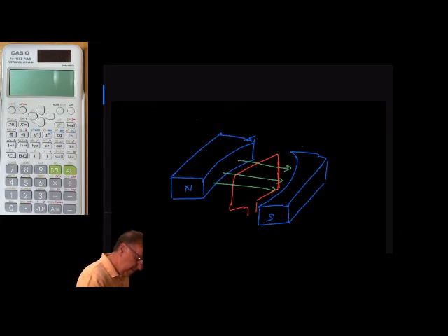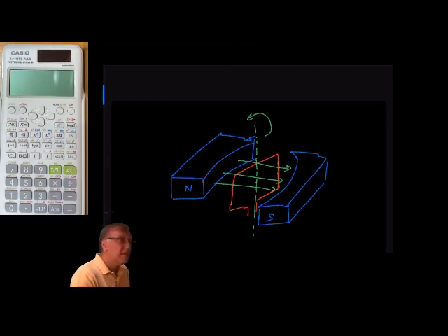And we'll have an axis. That wire will spin around the axis of the rotor in this direction. So basically what we've done here is we've inserted a coil of wire between the two magnets, free to pivot around the axis. So the coil rotates and a sinusoidal current is produced in the wire. So let's look at it again in 2 dimensions.